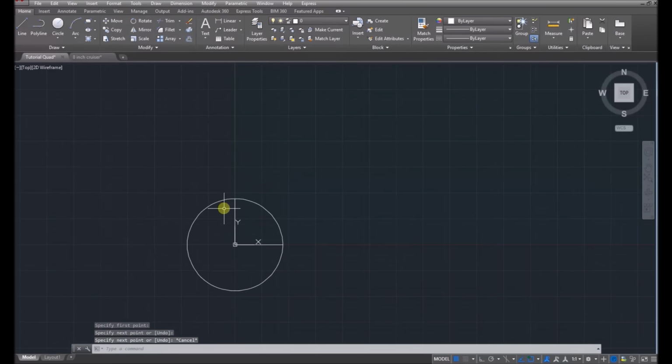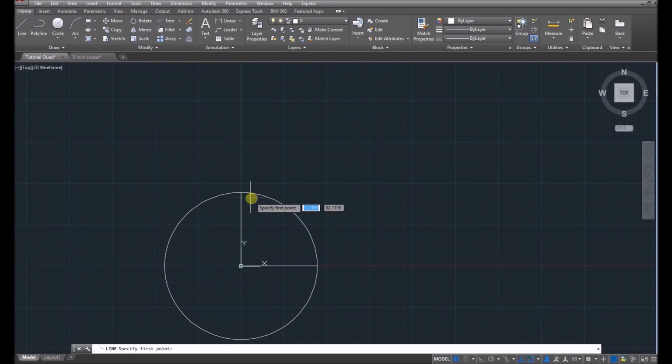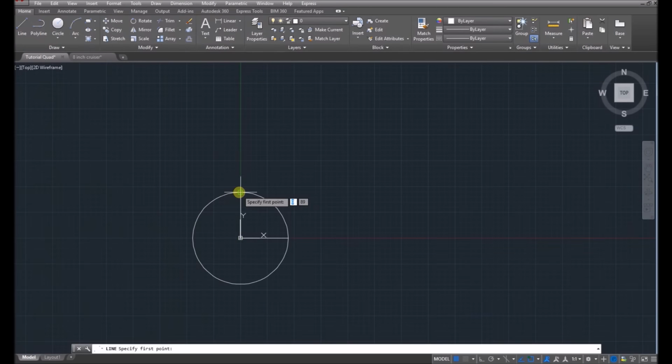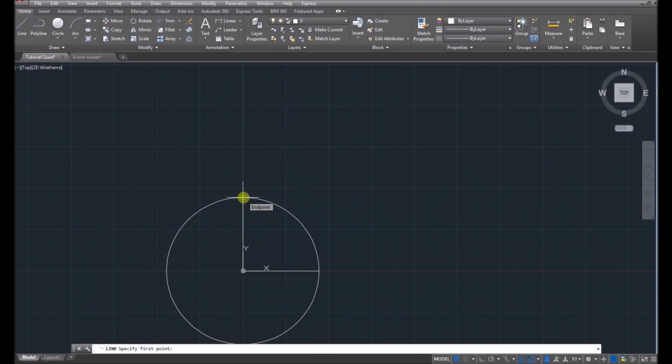Right, so I will do that. Now, I'm going to have an H frame, with a prop up here, 2 props here, and the body's going to be this way. That's just how I'm going to design this frame. So, distance in between props. For 7-inch props, I'm thinking I would probably go 10 millimeters, draw a line. So these are just all marking lines that I delete later.